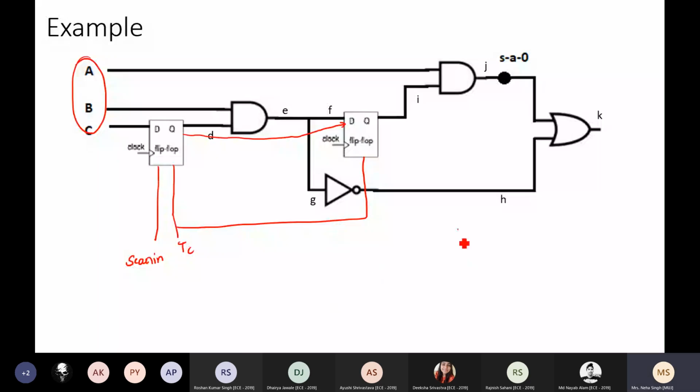This scan design is very important when we need to test the boards. The reason being, when we are making boards, multiple circuits are combined together. Multiple ICs, in fact, are joined together to form a particular big processor. All those ICs may be working with different sizes, may be working with different nomenclature, but every time we need to have something done so that all are considered together. So when we are testing for boards, we use this scan chain design as boundary scan. I check the outputs and input compatibility using the scan chain.